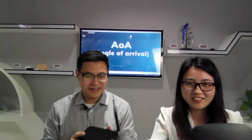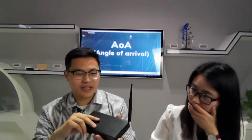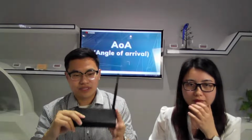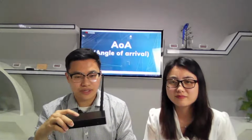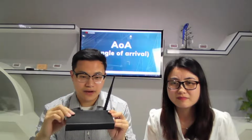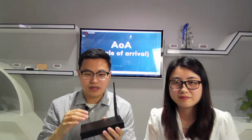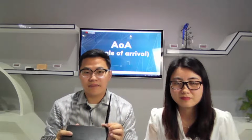Of course. This is the G2. We can say the gateway. You can call it an IoT gateway if you want. So what do we do with that? It plays an important part in transmitting the Bluetooth data collected by the locator, and it transmits the data to the cloud. We put the IQ data through the gateway to the server through the MQTT protocol and the TCP protocol. Anything else? Of course, we also have a power adapter.